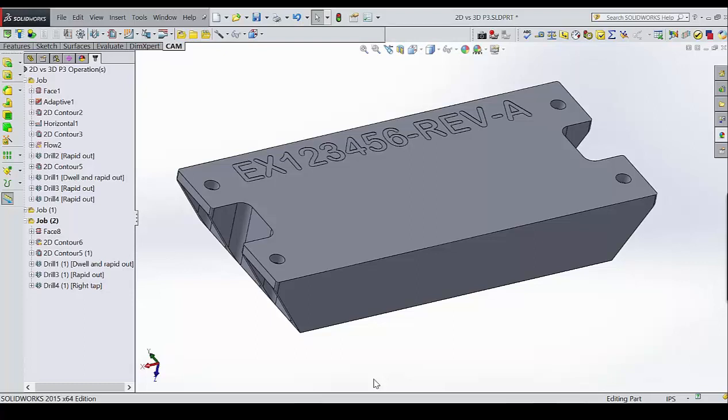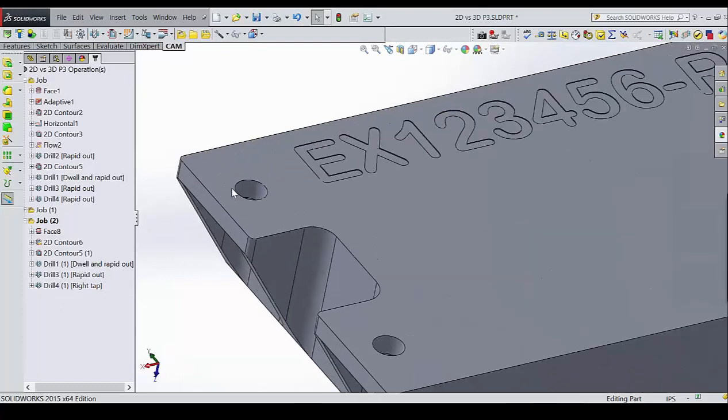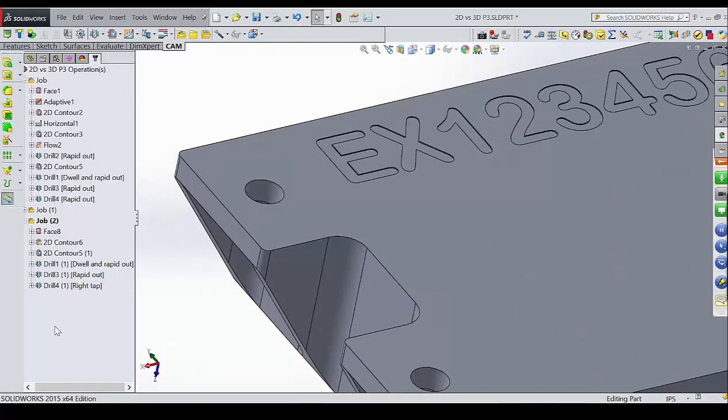Awesome. Okay, perfect. Brian has a question here. Multiplying a specific value by 0.288 is interesting. I'm using 2 chamfer width. Is that basically the same thing? So there are 2 ways to approach it. In this model, the chamfer is not modeled in. If your part has a chamfer modeled in, that's the other way to set it up: in your geometry selection, you'd be selecting the chamfer face. So that's definitely another good way to set your chamfer depth.